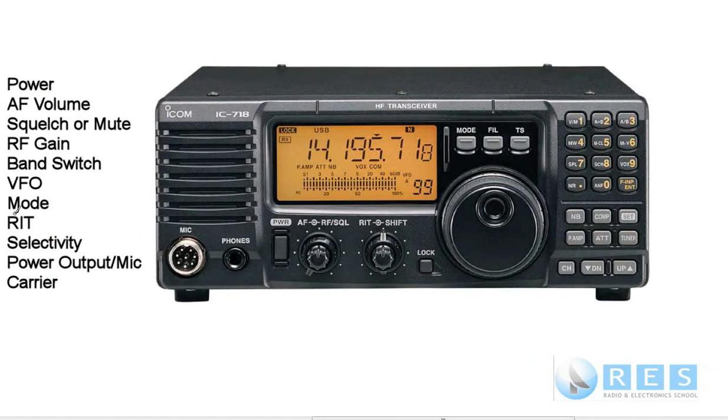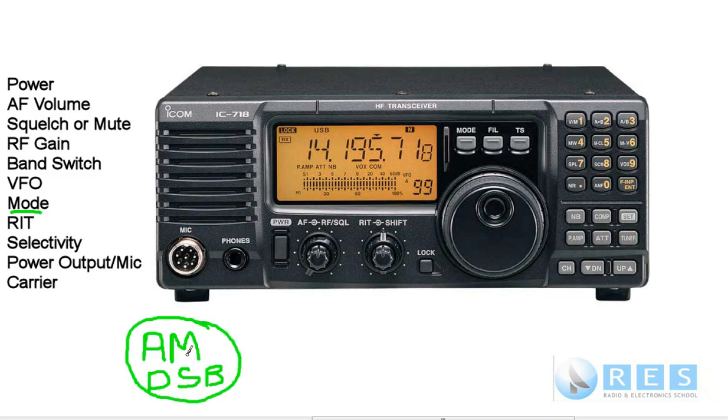The mode. The mode is the mode that we want to transmit on. The common modes are amplitude modulation, that's double sideband. We call double sideband amplitude modulation. That's really a misnomer because AM is really double sideband, which is the proper name for it. But it's commonly referred to as one and the same. So your mode switch is how you change to AM or double sideband or single sideband.